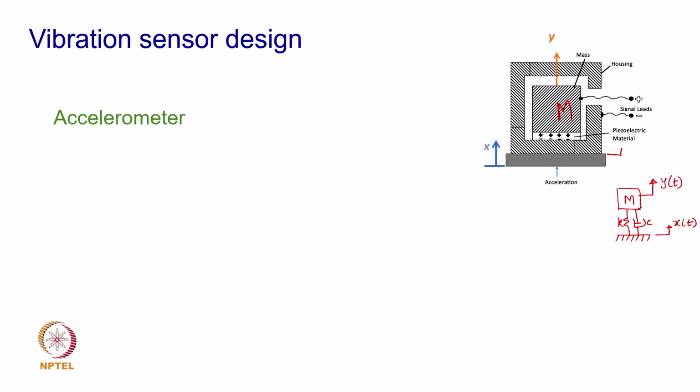Now, when the piezo material is compressed and generates a mechanical strain, the output is a charge which is taken out. What you can notice here are these leads which are connected to the mass as well as to the base. From the base or the housing, one lead is coming out, the other one is through the mass. So, the charge travels from both ends and then you collect the charge as an output. Based on the compression in the disc, the charge output is proportional to the mechanical strain in the discs.